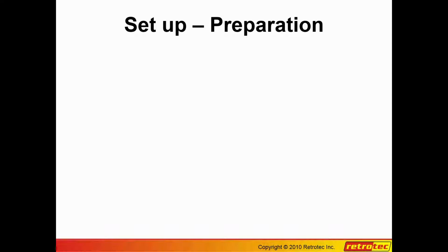The way I look at any exhaust or supply flow devices, I don't look at it as being a hole, because it doesn't act as a hole. I look at it as being a flow that's going into or out of the building. Unlike, say, an intermittent exhaust fan that is open 99% of its lifetime, with the fan not running it's basically a hole in the enclosure, and the hole affects the performance of the building. So it spends 99% of its life as a hole and 1% of its life as a flow device. That's quite different from a continuous ventilation device, which we really won't be looking at as a hole.